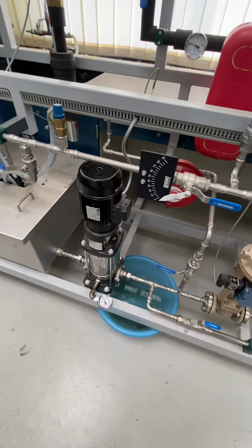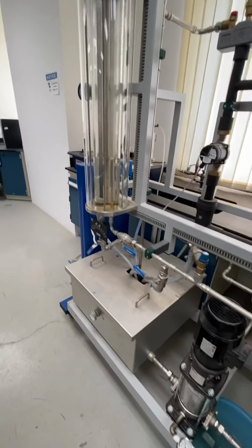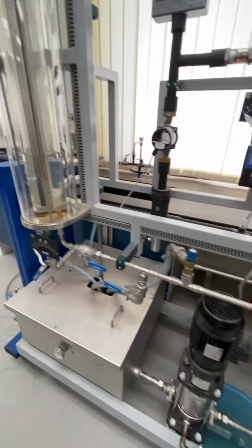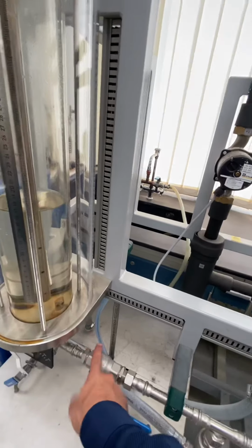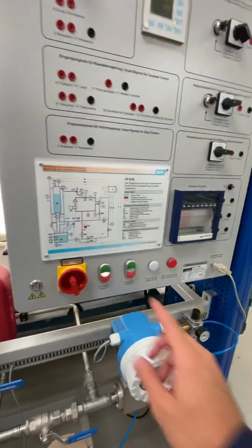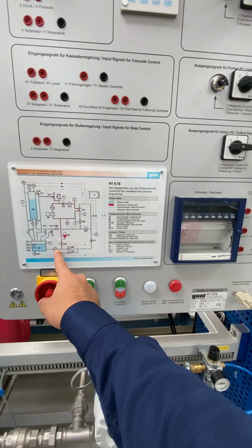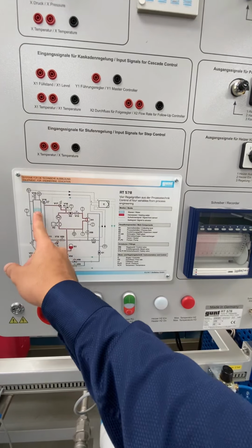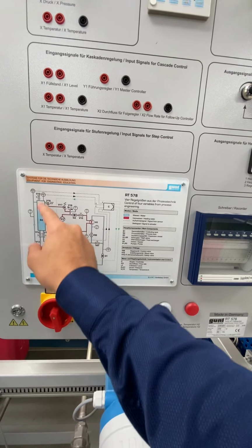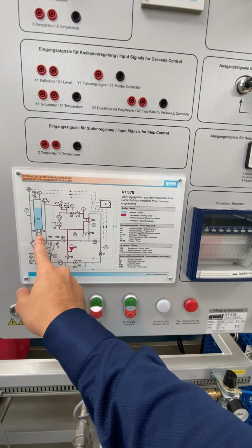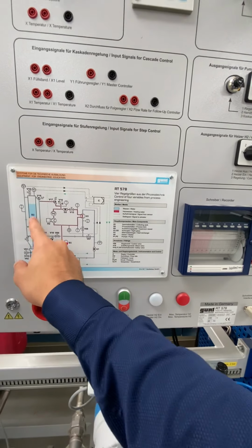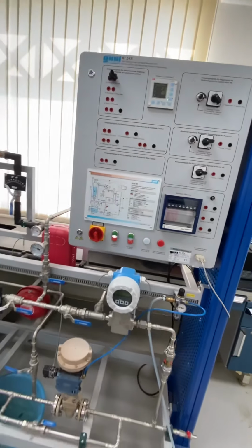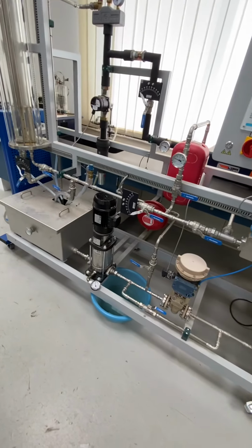Okay, now the dangerous thing about this situation here, guys, is that if the discharge pressure at the pump became less than the pressure here, let me try to show you through the process flow diagram. If the discharge pressure here at the pump became less than the pressure here, we know that there is water inside the tank, and that will create some static pressure. So if the pressure here became larger than here, then we will have a reversed flow, and that is a serious issue when it comes to pump operation.